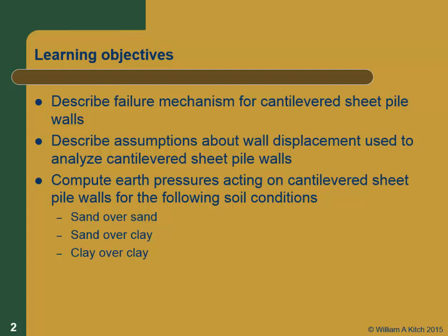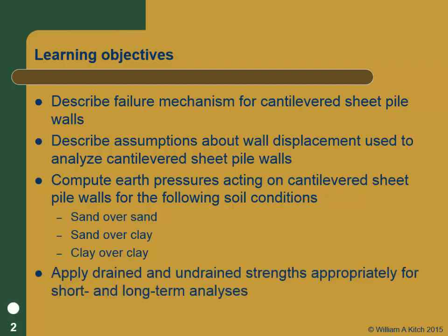Particularly if you're in a marine environment, it's real common to have clay soils, and you're going to have to install the wall into clay soils, and you're not going to get rid of them. So that's the reason it's really important that you understand when to use short-term undrained conditions and drained long-term analyses.